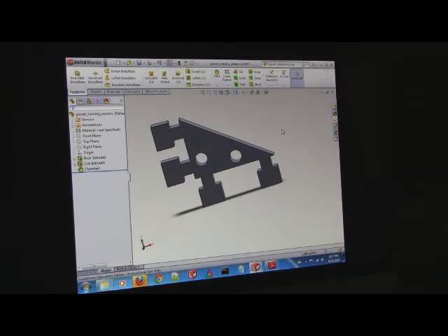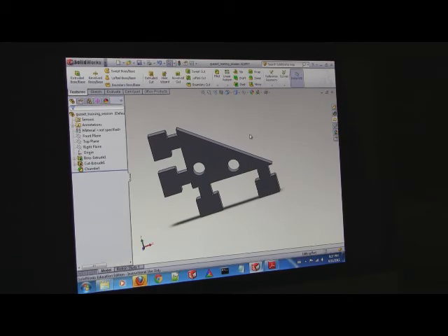So that is one of the parts for Lab 1. Is everybody good with that? Has everyone chamfered and put their circles? What's the dimension on the circles? A radius of 1 or a diameter of 2. You mean the circles, the edges? Yeah, just the edges. And then change that to 1 millimeter. Yeah, and just select the edges that you see on my screen. Highest diameter, right? And you remove the copy? Yeah.